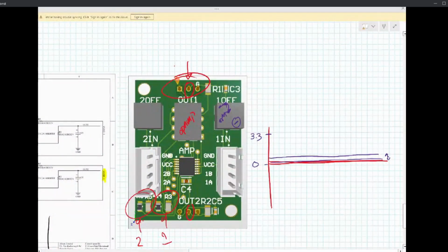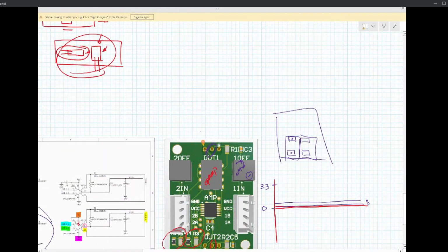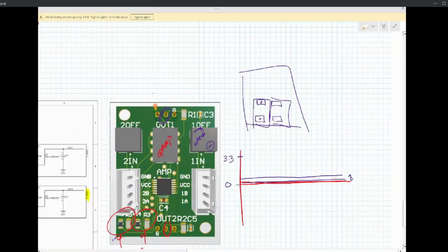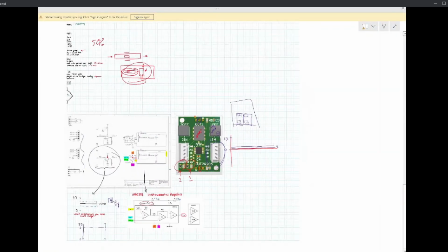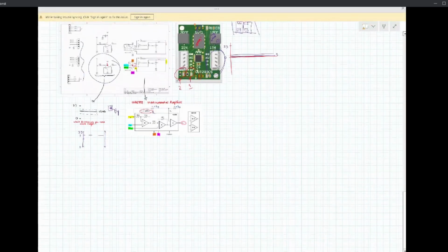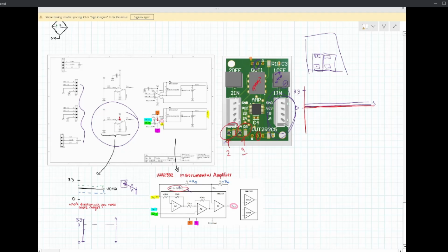It sits in the DAC box, so if you can picture the DAC PCB, there are some DuPont jumpers that are here and here, and this PCB just sits right on top of those. So it's getting 3.3 and ground right from the DAC PCB, and then it's taking in that analog channel right in the middle, so it's pretty cool. And then we fabricate wires to take us from the PCB all the way to the Wheatstone bridge that we make on the tubes, or wherever they end up being. So that is where we were at the end of last summer, for the most part.